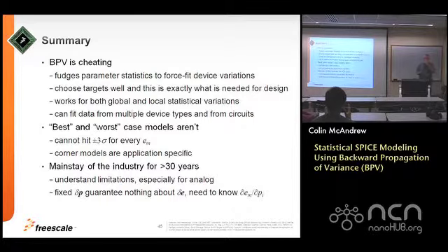So you compare that output with your target, right? That's done for tuning the typical case and the corner models. A nonlinear optimization will then adjust the parameter values so that the targets match. But for the statistical characterization, from the outputs as a function of the inputs, we actually do perturbations on the inputs to generate the sensitivities and then analytically solve the equations.